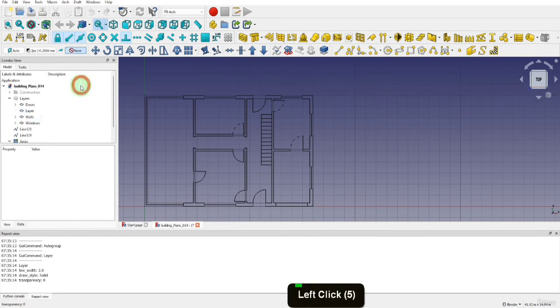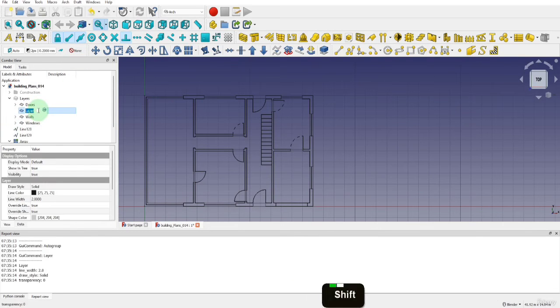First, we can create a new layer. Now double-click and rename this furniture. We can make this active, but when importing objects, they get added outside layers. Imports also get imported in a great number of shapes, so we can try organize these by using groups. The benefit of groups is they can be stored inside layers, whereas layers cannot.